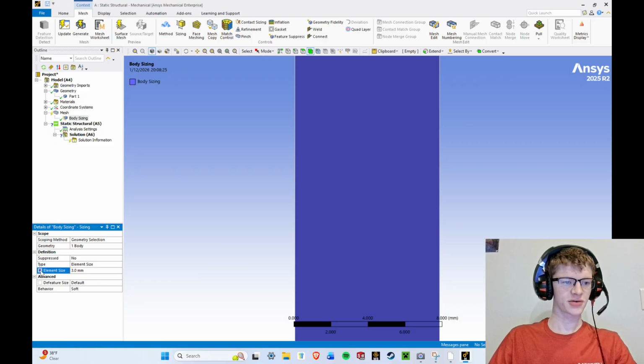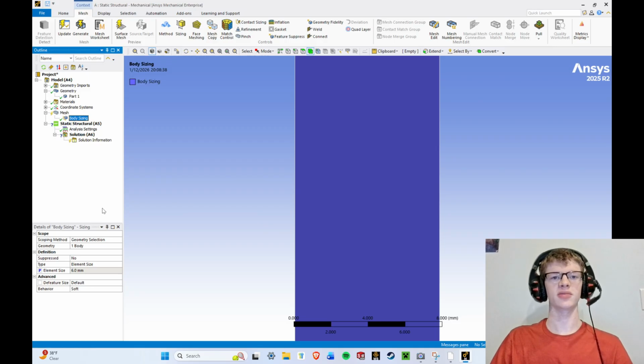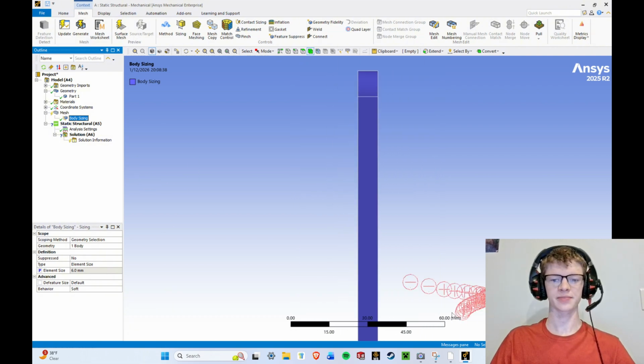And we're actually going to parametrize this as well. We're going to do, actually I'm going to change this. We're going to do a 6 millimeter mesh, and then we're going to do a 3 millimeter mesh for whichever of the two materials, aluminum or titanium, actually allows the phone to survive. And then we're going to refine the mesh for that one that survives to see if the results change significantly when we use a finer mesh.